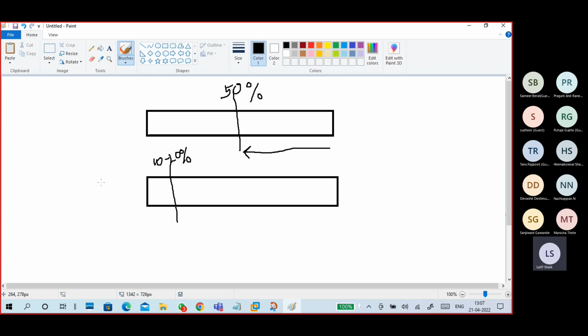A heated battery will damage the surrounding circuit, because in the earlier days the battery was very adjacent to the motherboard, very near. So the heat is on your laptop circuit. It is SMD devices, SMT technology. So the soldering on it is also not very strong. It is strong, but only up to a particular heat level.